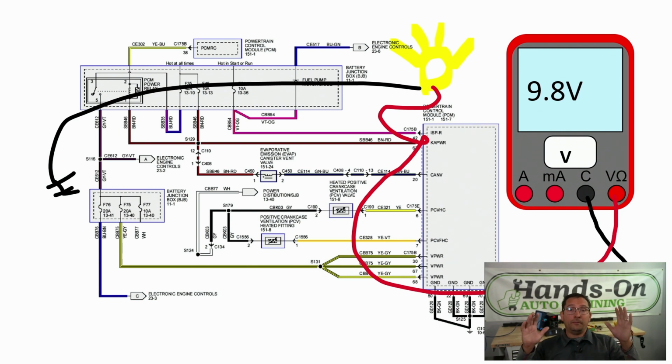There's no doubt in my mind that as we're increasing the load, we're trying to put more of a load on a circuit, which means more current flow. If we increase our current flow, our voltage drop is going to go up over even a normal piece of wire. But if we have a bad section in the wire, we're going to see a really big voltage drop. And that's what we're seeing here as we load this circuit up.